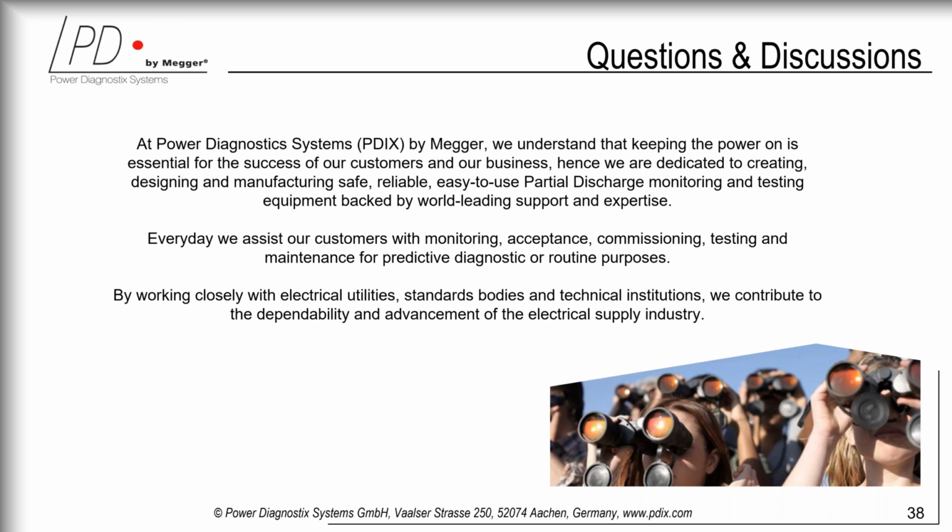Yeah, and one more failure case we have on bushings. If failures happen in, let's say, cracks in epoxy of the bushing, they will not show up in the DGA, but they can be measured by PD technology. That means with a partial discharge measurement technology and monitoring, we will see even more failures and issues on transformers than with DGA, which shows only failures related to oil or close to oil, so that the PD produces gases.